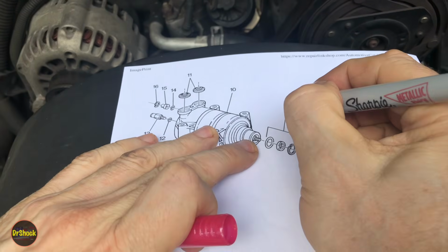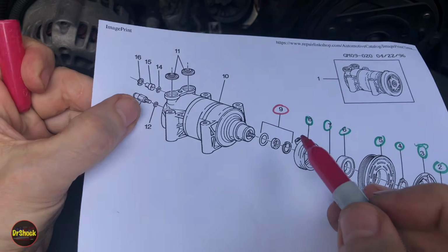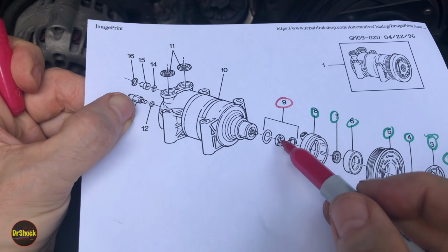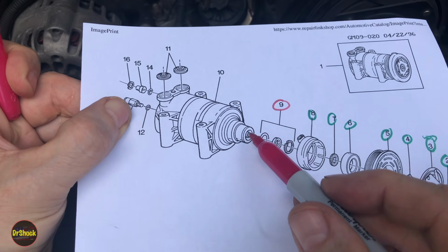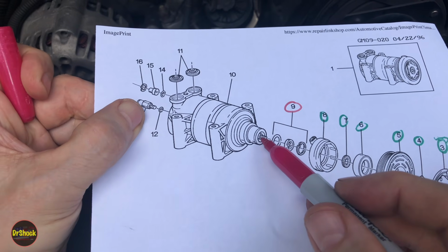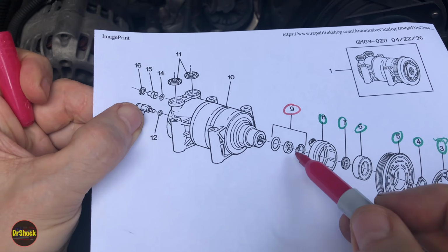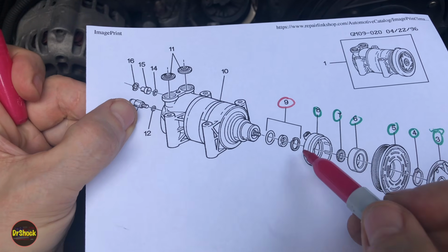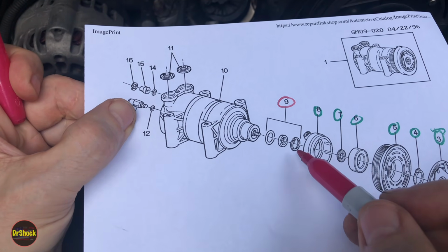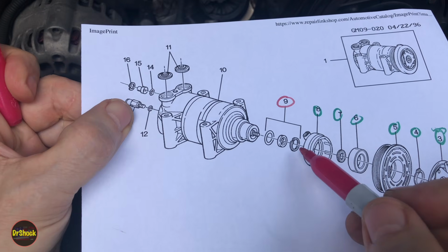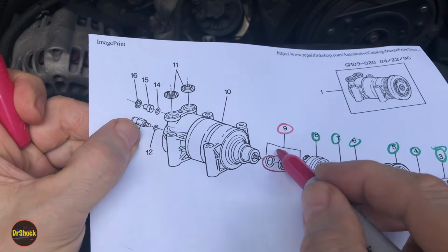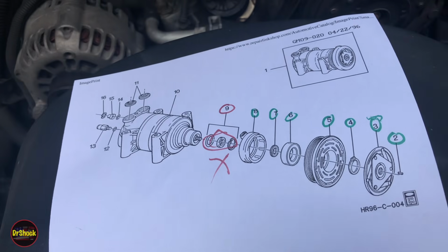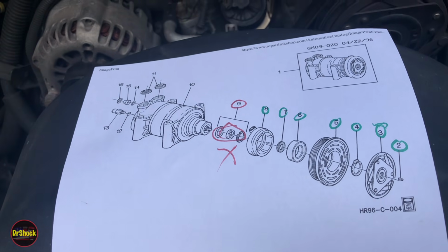This piece we can't, because if you accidentally remove this snap ring here, that's a seal and an O-ring retaining the refrigerant inside the compressor. That's a shaft seal assembly. If you do that, you're going to get injured because this stuff's going to violently shoot out. Frostbite, blindness, fill in the blanks, and whatever gets hit. You do not want to touch this stuff. This is a big do not touch. But all of this we can work on the vehicle without evacuating the refrigerant.